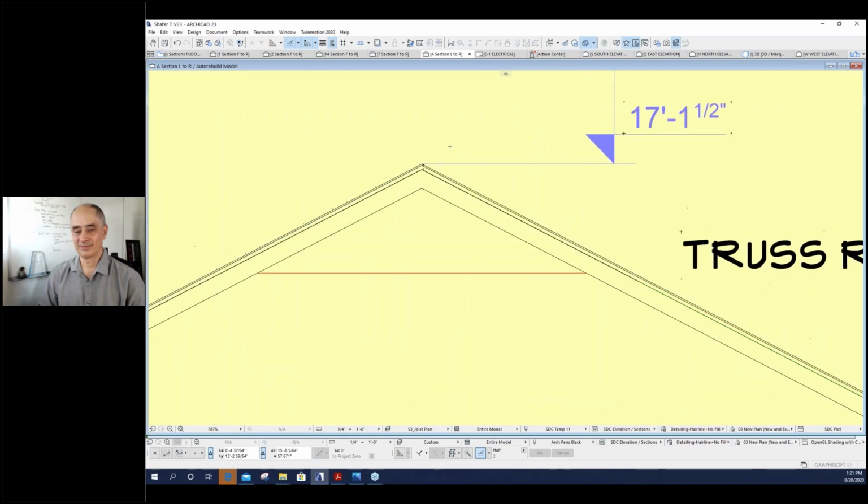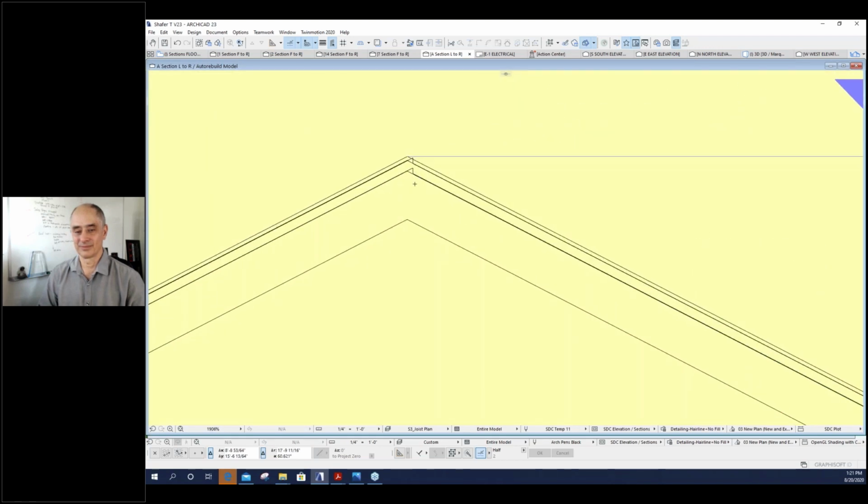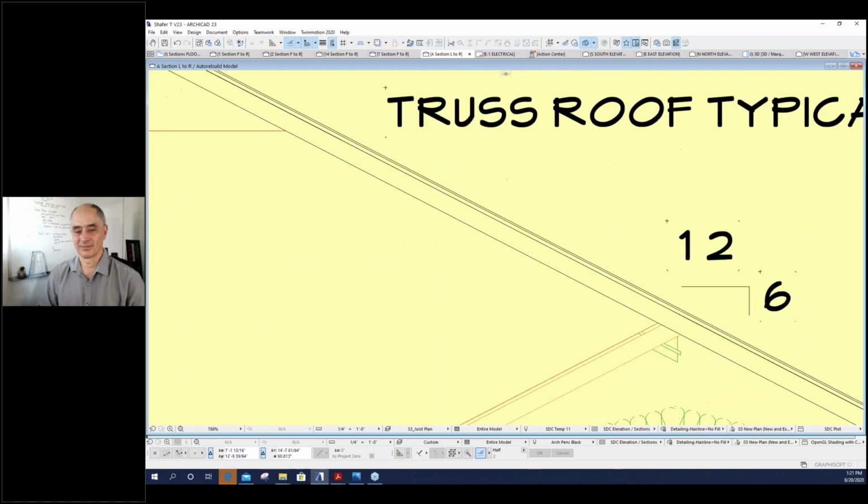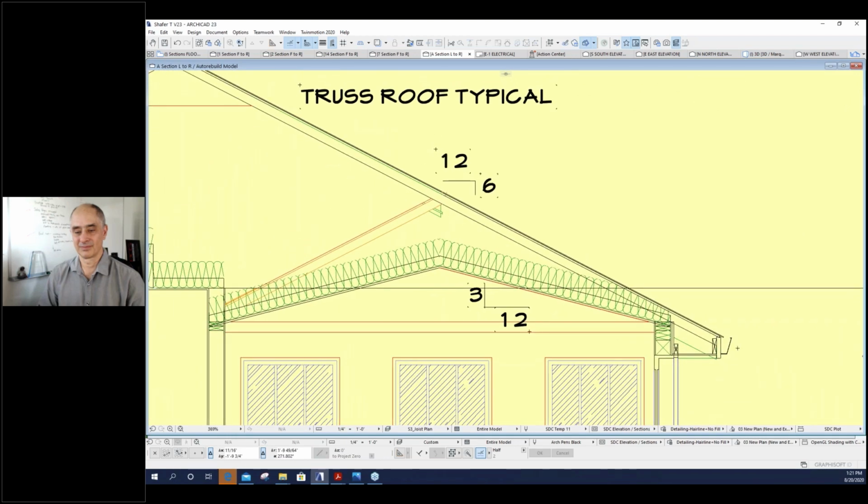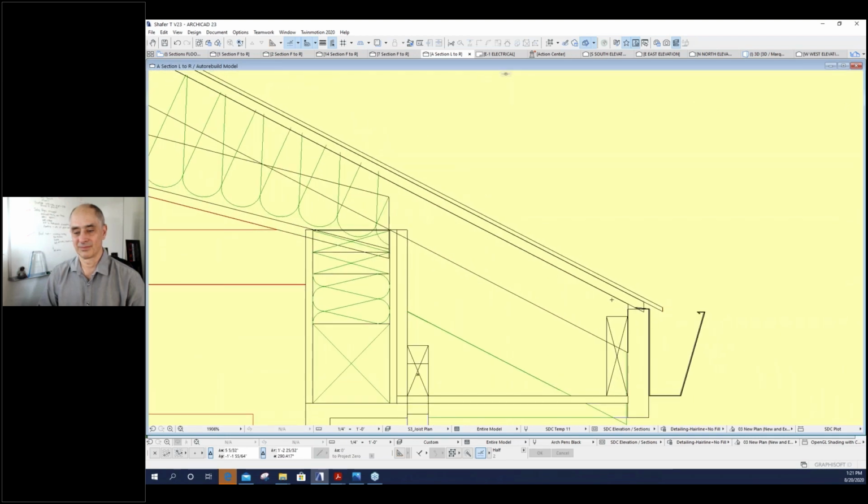So you can see I put in a separate truss and then plywood and then a comp. And the reason I do that is down on the ends, where the truss stops behind the fascia, the plywood comes into it, and then the roof comp goes over the top. So Roger, can you just select each of those so we can see that they are separate elements? Because I want to make that clear.